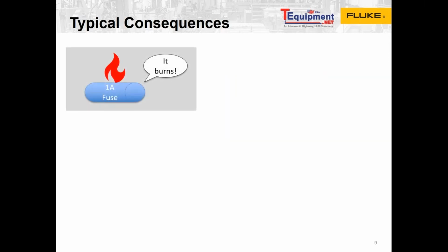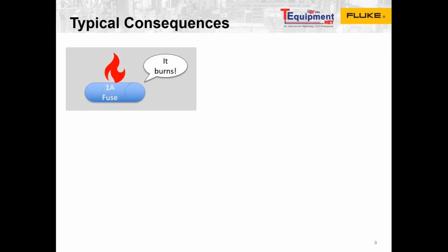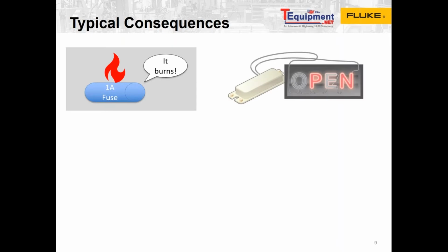So there are many consequences of not addressing power quality issues. There are power failures such as nuisance circuit breakers tripping or fuses blowing. LED indicators on drives have also been known to blow out. Another consequence could be flickering lights. Exactly how you're seeing here, maybe the office lights are flickering, and that can cause human health issues, causing migraines or causing people to go into epileptic shocks. So we definitely want to avoid that.